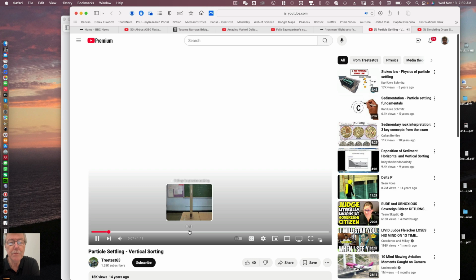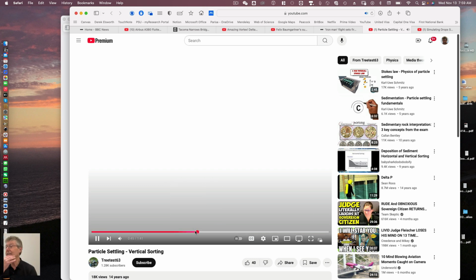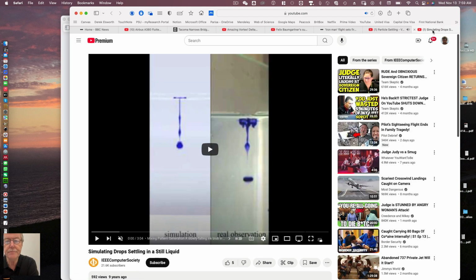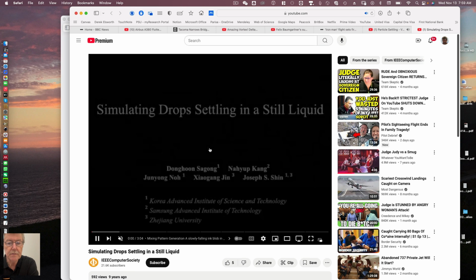Okay, one of the more mundane things that we use external flows for is getting the gradation of fine-grained soils. It's difficult to sieve them, to have a sieve that's small enough mesh to get it through. So one thing you can do is put it in water and let it settle, and you can calculate how long it takes to settle in a graduated cylinder. The rate at which it falls is proportional to the diameter of the particles. So, let's see if this works.